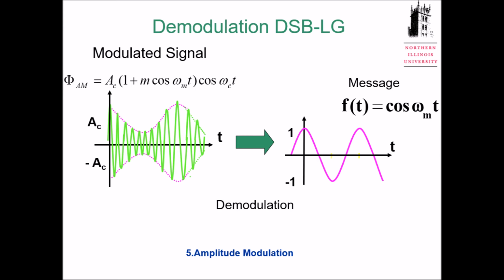So I'm going to catch those envelope changes according to the signal. Once we choose my R and C very carefully, we get the signal extracted, demodulated. So this is a huge advantage. Even though we have a huge disadvantage here.